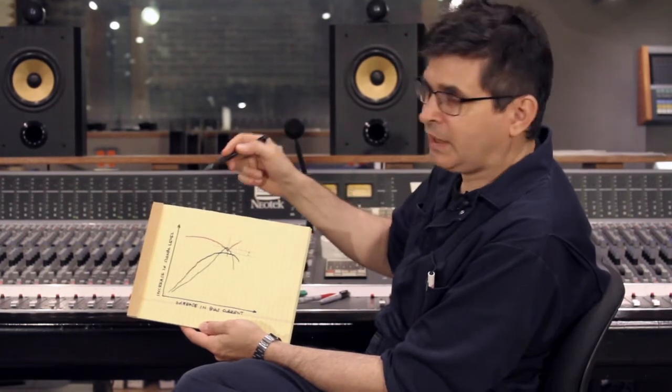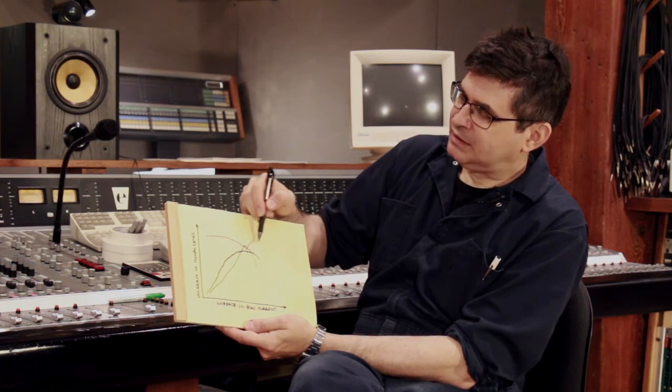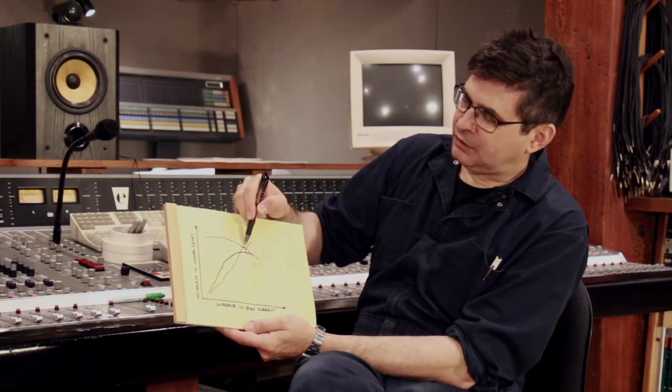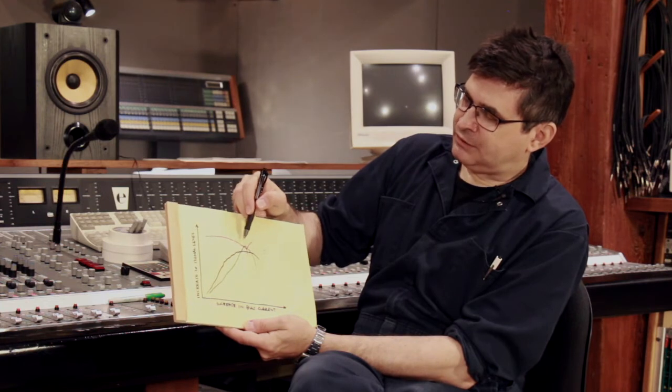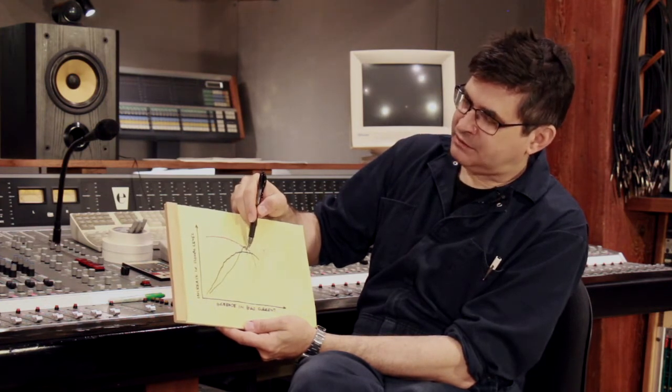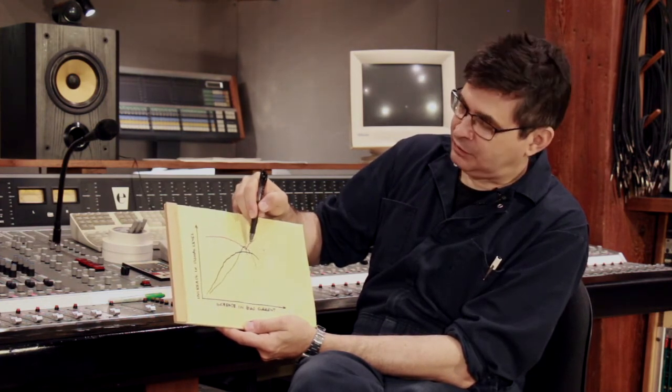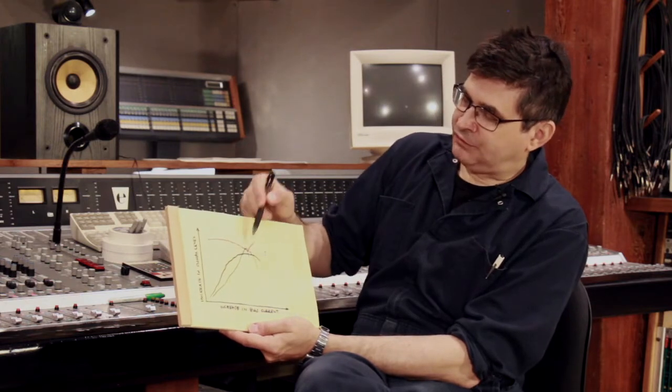These values are published, so for example, for any kind of tape you can find the recommended amount of overbias, and this figure is described as overbias. So for example, if this is a 10 kilohertz tone and you find that at a given speed, say 15 inches a second, you reach the point of minimum noise and distortion when you've lost 2 dB of sensitivity in the high frequency tone, then you would describe that as 2 dB of overbias at 10 kilohertz. And that would allow you to find the optimum bias point for that tape machine.